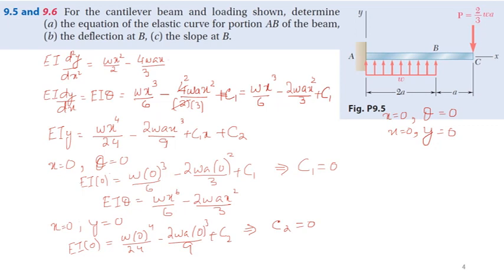Now the equation of elastic curve, EI y, will become Wx to the power 4 by 24 minus 2WAx cube by 9.